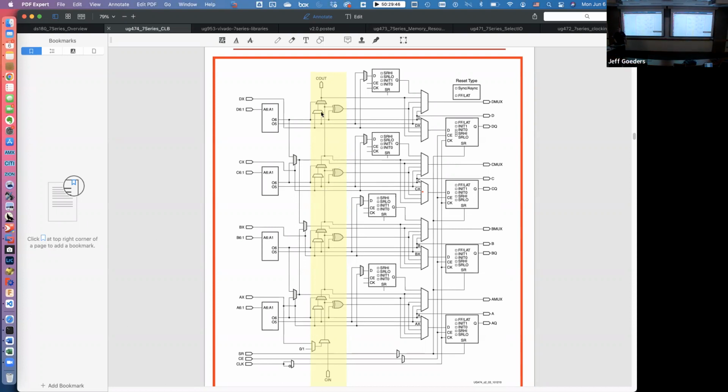Okay, so if you look and you say 2 muxes in an XOR gate, how in the world does that help? You'd have to go read up, but as you might guess, Xilinx has documentation on how they often implement adders. Okay, on the left side, we have all these inputs. We have a DX and we have 6 inputs to the LUT. Then we have a CX and 6 inputs to the LUT and so forth. In the lower left, can you see we have a clock enable and a set reset signal way down here. Where do those signals come from? How do they get into the slice?